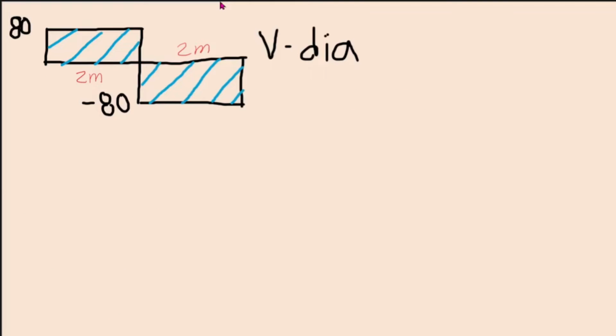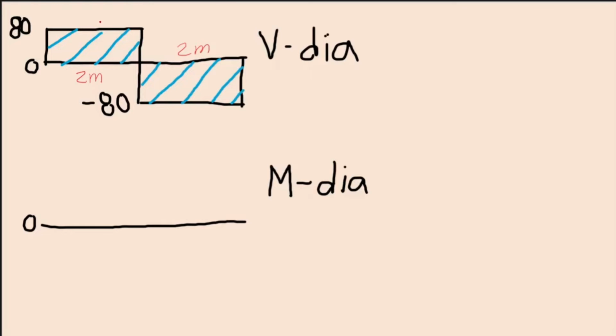And so now, we can move to the moment diagram. Again, we will first establish our zero line. This will be 0, and then we will draw a line. Now, this is a positive constant load. If we have a positive constant, then if we move 1 degree, it becomes a diagonal line. And the direction will depend on the sign. If it's positive, the diagonal line will go up. And if the load is negative, our diagonal line will move down. Because again, the n here will be 0, since this is just a straight line.